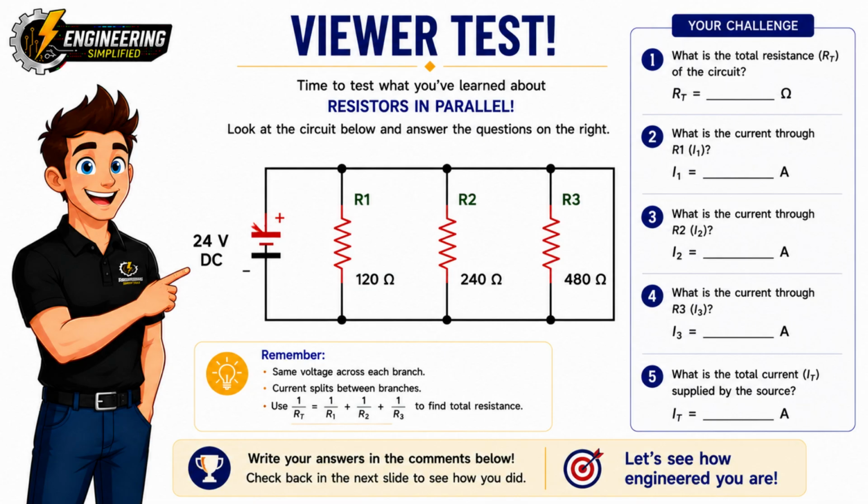Before you start, remember the 3 key rules for parallel circuits. Every branch has the same voltage across it. The current splits between the branches depending on the resistance of each branch. And to find the total resistance, you must use the parallel resistance formula. Don't just add the resistor values together like we did in a series circuit. Take your time, pause the video if you need to, and work through each step carefully. If you can solve this circuit on your own, you're building exactly the skills that electrical engineers use every day. Once you've finished, continue to the next slide and we'll compare your answers with the full worked solution, step by step. Let's see how you got on.